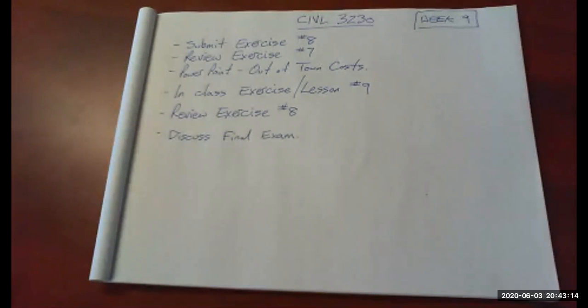So that's the total. Down here, you were given the overheads. So there's your overheads, there's the total. So the reason I did this calculation, so total overhead divided by total cost of estimate, 6%. That is how I prorated the amount of overhead that goes into each bid item.